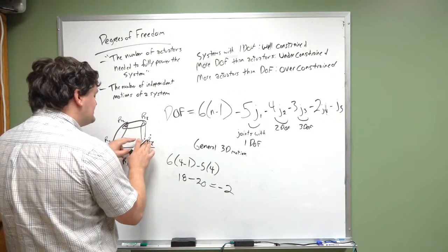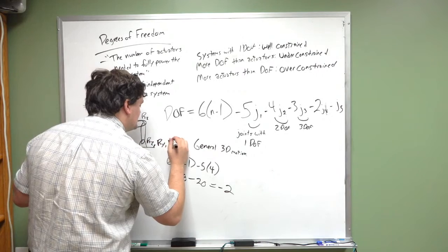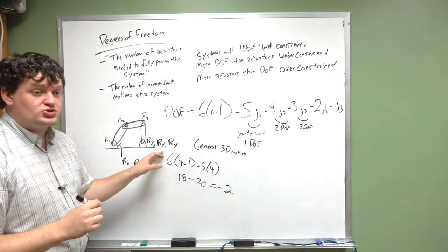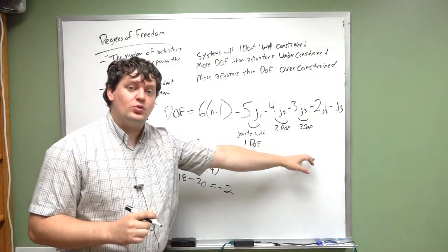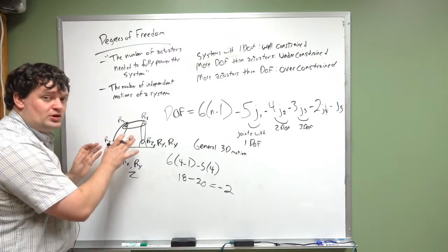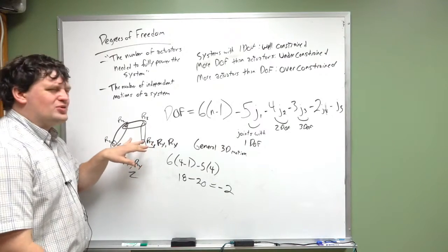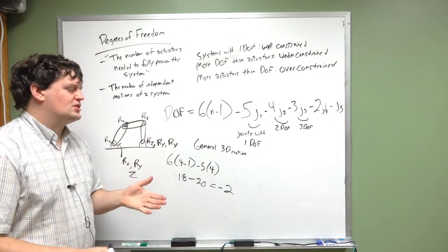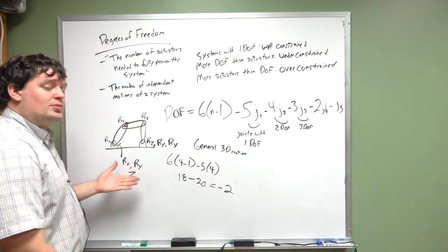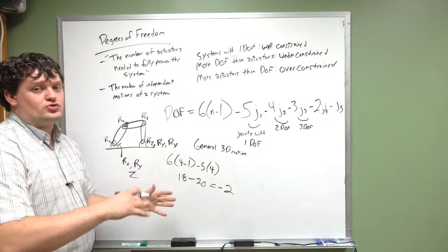If you were to replace this joint and allow Rx, Ry, and Rz rotation, turning this into a ball joint, that does change your general equation overall. And it also means that all of those forces are going through only 1 pin. And you know, if you want to design this to handle that, great. If you want to leave this as a planar linkage, that actually doesn't cause problems. Even though in the general 3D equation, this 4-bar linkage has negative 2 degrees of freedom, those 2 degrees of freedom are being taken out in the other directions.